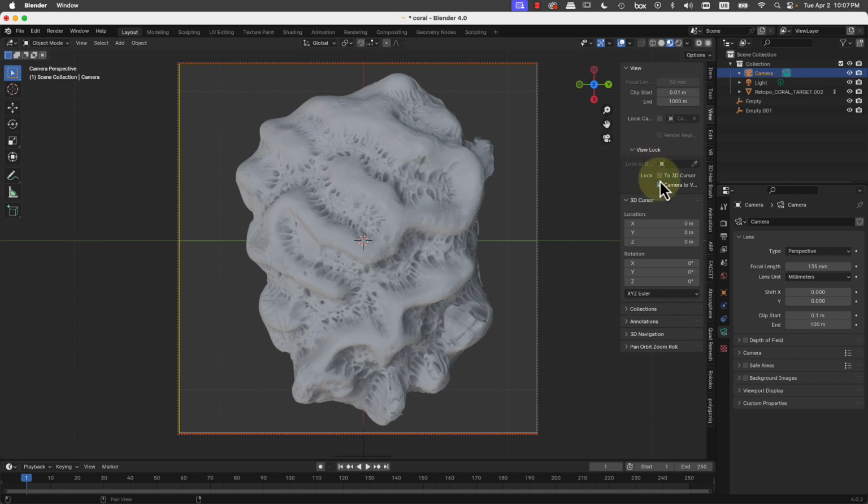Great, so I have the camera there, I'll keep the camera, and here comes the weird part. I want this to look, and then realize that I'm using viewport shading here. I want this to look as a grayscale image where the parts that are closer to me are whiter, and the parts that are further away are darker. It's a way to encode the distance between the camera and the object.